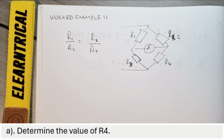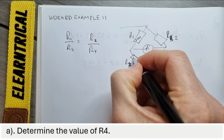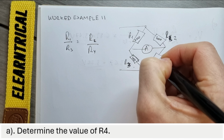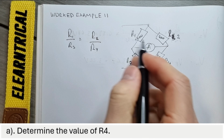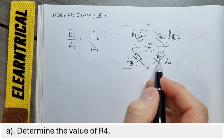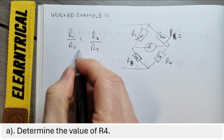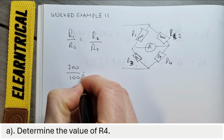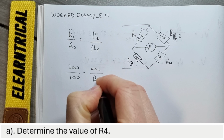Speaking of which, in the question we have 200 ohms here, we've got 100 ohms down here, 400 ohms, and our unknown resistance of R4. So in order to calculate the unknown resistance of R4 when the bridge is balanced, we can use our equation here, 200 over 100 equals 400 over R4.